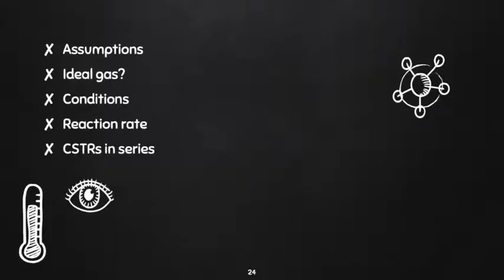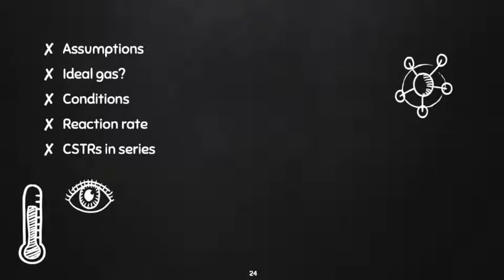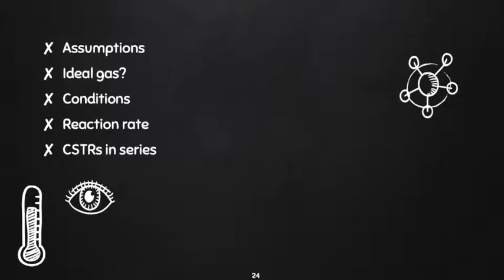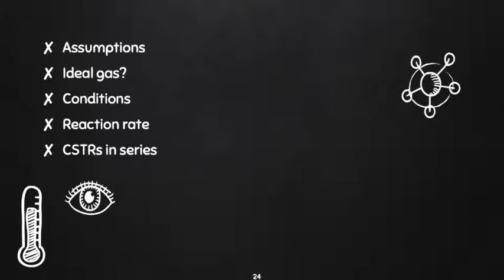It is important to start with the fact that the calculations were based on different assumptions. The first one is that the olefins, being the limiting reactant, behave like an ideal gas. For the calculation of the molar flow rate, we use the conditions that we had previously established from our research. And with those parameters, a molar flow rate of 74.032 moles per second is obtained, which we consider is a small number for the process.